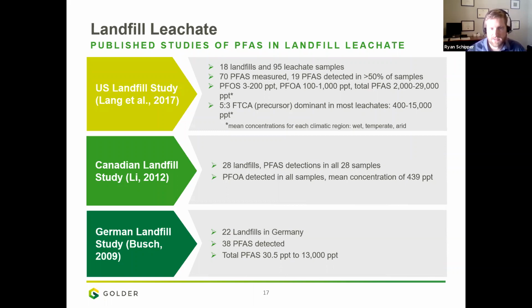The PFOS, I won't go into all of them, you can see them there, but I will note that in some cases, landfill leachate can have PFAS concentrations all the way up into 100,000 parts per trillion for some of those landfills that have maybe taken direct sludge from PFAS manufacturing, or were near some of those manufacturing facilities, and they could have taken sludge from a municipal wastewater treatment plant that treated some of those byproducts.